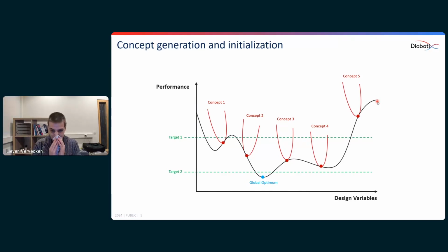For that, we'll use some smart features of the generative design software. The first one being concept generation, where you a priori select a given design philosophy, pins, fins, gyroids, and then quickly evaluate a bunch of different options. Because you use conventional cooling solutions, correlations can be used to quickly identify the performance and generate a bunch of different data points, so that you can get an idea of what this black line looks like.